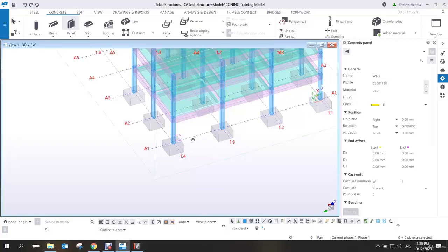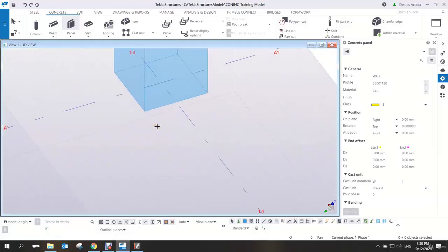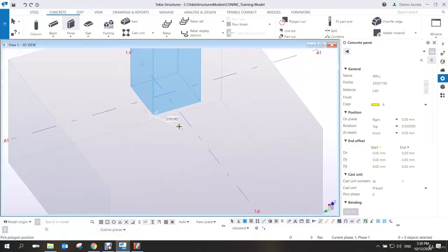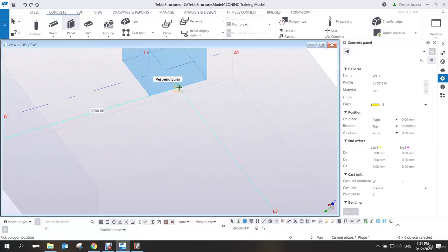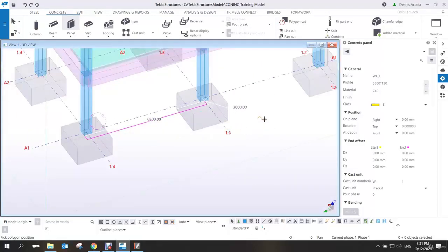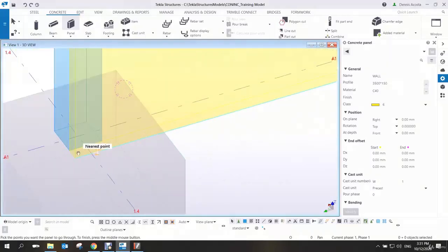Yeah. So you can press Control 1, Control 2, Control 3, Control 4, up to Control 5, Control 1 to 5. So those are the different views. Control 1 is wireframe, Control 2 is a shaded wireframe, Control 3 is white, Control 4 is solid, Control 5 is something like a ghost image. Okay, so let's say if it is Control 2, so look, I can easily click on this point, right? 1, and then to the middle, 2, and then middle button of your mouse, because this one is a panel. So there you go.